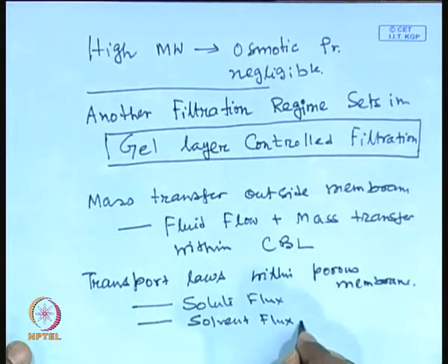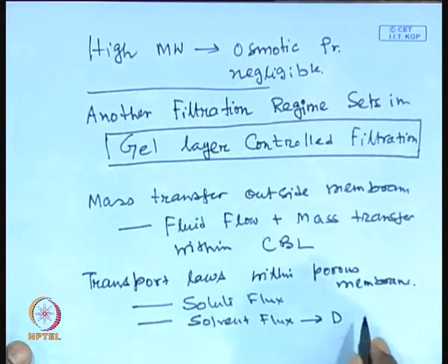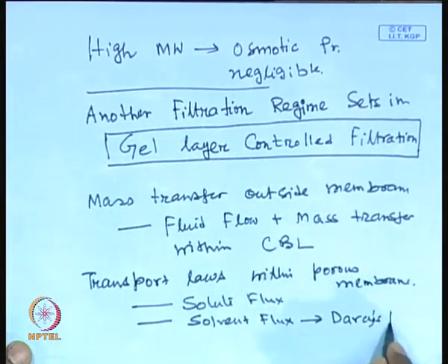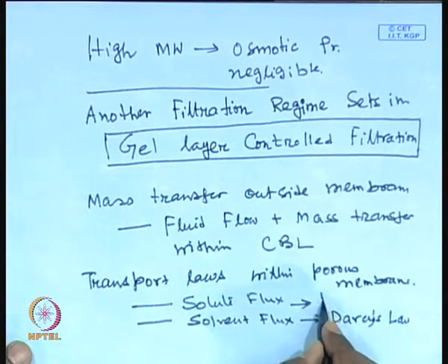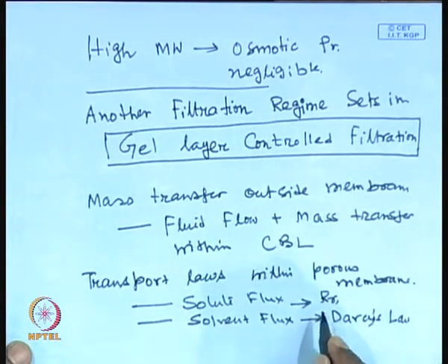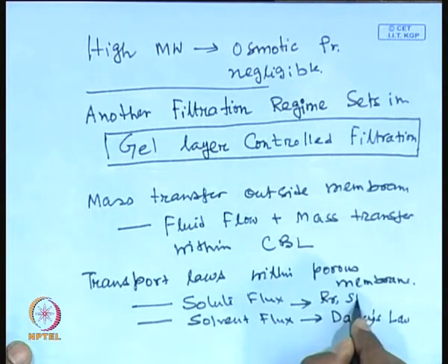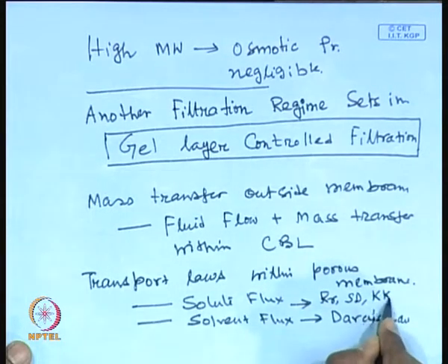Now, this solvent flux is generally, for all the cases, quantified by Darcy's law. On the other hand, the solute flux is given by either a definition of real retention or by the solution diffusion model or Kedem-Katchalsky model, modified models.